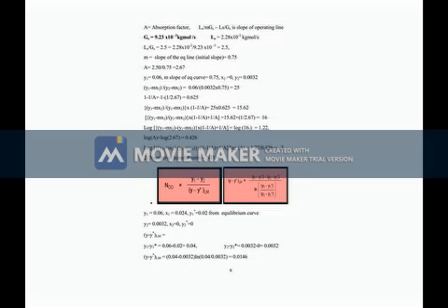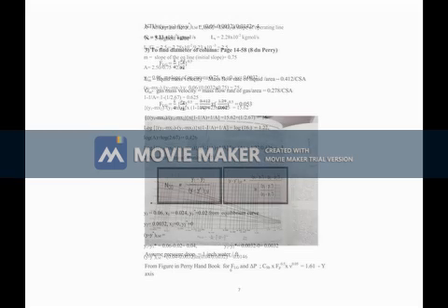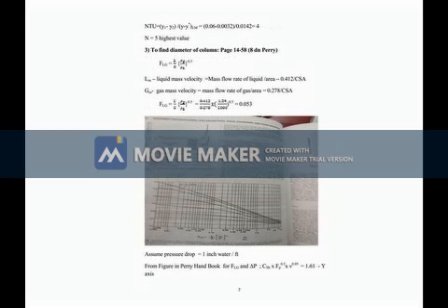That is G1 into 1 minus y. How will you find GS? GS is equal to G1 into 1 minus y1, that is 9.82 into 10 raised to minus 3 times 1 minus 0.06. So you will get 9.23 into 10 raised to minus 3. And LS, the liquid flow rate, is again 0.412 kilograms per second. That you have to convert into kilomoles per second by dividing by 18, which is for water. So whatever parameters are given in the question, we have represented here.